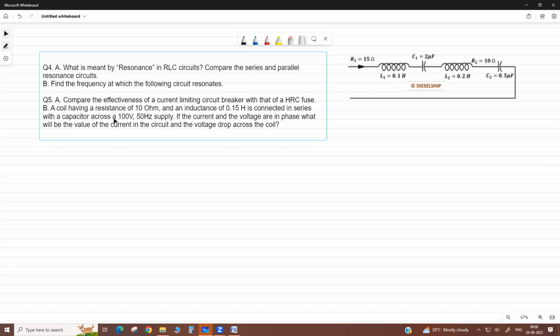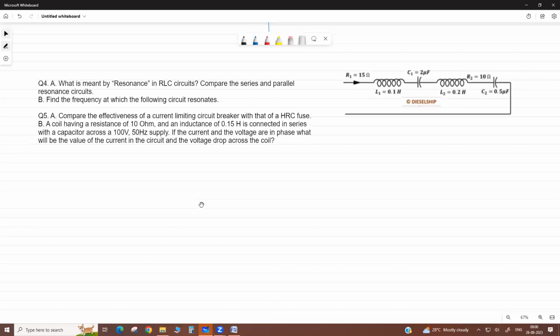Okay, here I put a, see. If we read the comparison, you take it in the group. Okay. See, series resonance is an acceptor circuit. Why? Because it accepts under resonance. It accepts more and more current, meaning high current. But parallel resonance is called a rejector circuit because its impedance is high at resonance in parallel. Then it rejects the current. It accepts the current in series resonance.